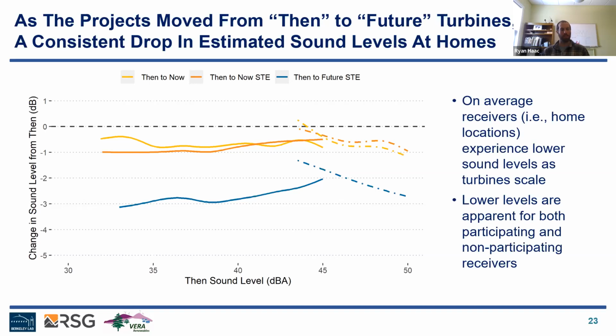Maybe it was minorly significant, but what I would say about the larger turbines is that there may be a concern when there's amplitude modulation, that now you have the serrated trailing edges, which in typical operation do a great job of reducing sound level, and certainly will reduce the sound level over a long period of time or for typical operation.